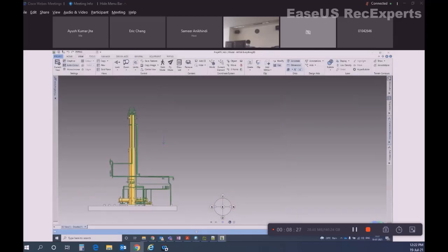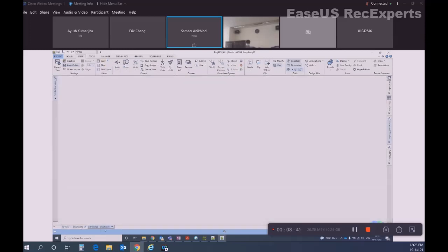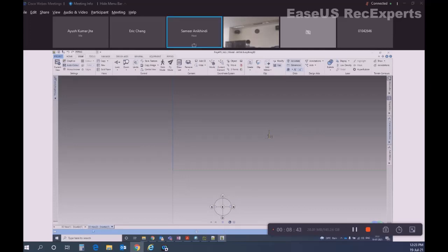I close that. Now what happens if I do copy to a clone view? Clone view means their draw list will be the same. If I remove something from one view, it will remove from the other view also. So this is clearly visible from 3D view 1, draw list 1, 3D view 2, draw list 1. So draw lists are common.